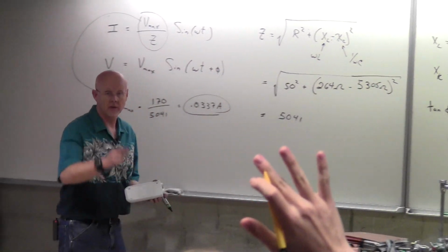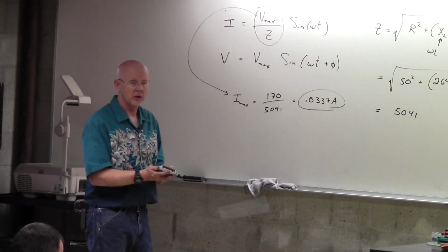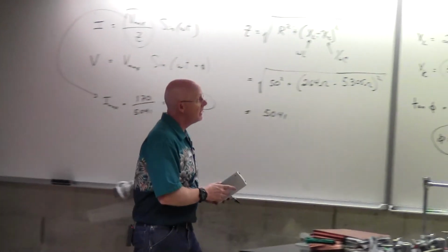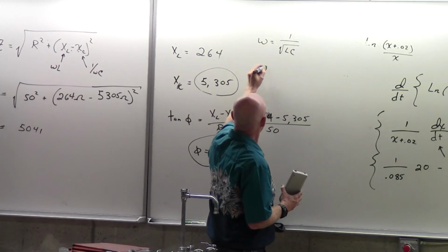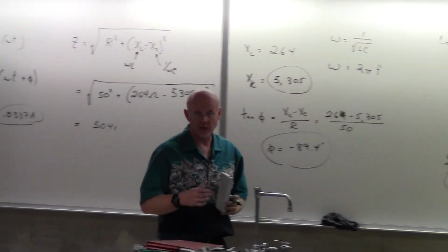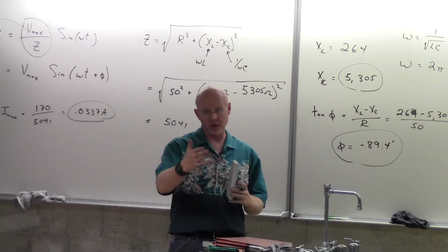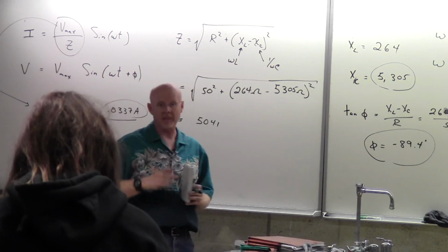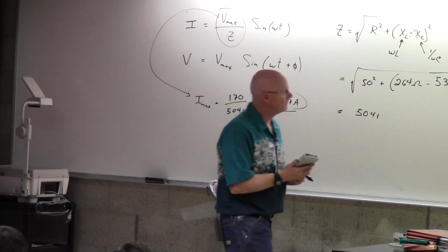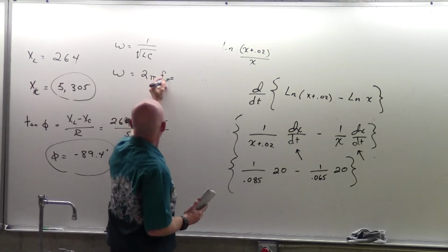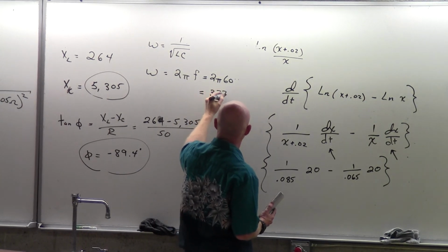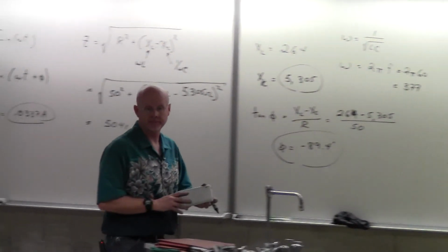How did you get the angular frequency? It's not a W, it's an omega, and the omega is the number of radians per time. So you take the regular frequency, and then multiply by 2 pi. So every oscillation is mathematically a 2 pi. So in our case, it was 2 pi times 60, which is 377.